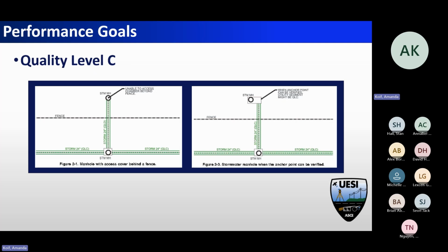Because this is straight out of the standard. So the one on the left is the level D line. I've got two manholes that are surveyed. So now, it's level C, right? Well, I didn't open that lid, but if I open the lid for that storm, well, that line's actually offset. So we were incorrectly drawing that line as level C on the left if we hadn't opened that. So opening those and doing the butterfly diagram or documenting every single manhole that you open, that way you can get the direction and size of how all the things are flowing together. So that's kind of a good example, and it's straight out of the standard of why you open those and how to depict those.